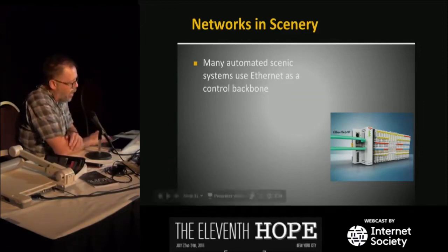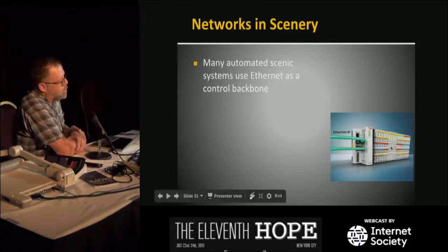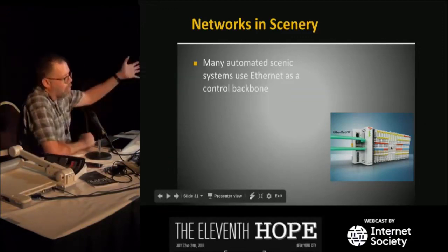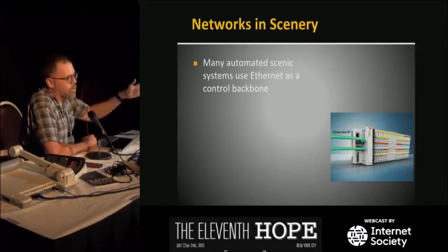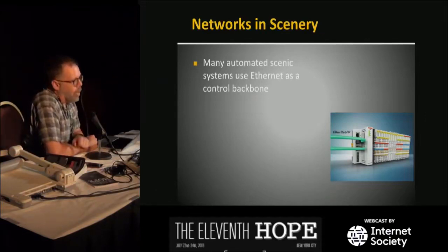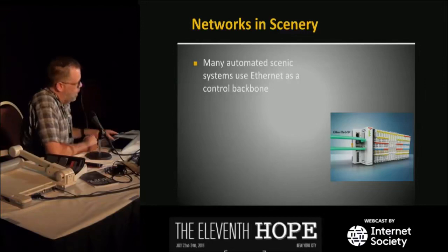And then this kind of box can provide whatever I/O you need. So if you want to have sensors over here in your dark ride, instead of running analog cable all over the place, you just run an Ethernet network, plug it into your box, and then wire into that box. That's what I was talking about, Beckhoff.